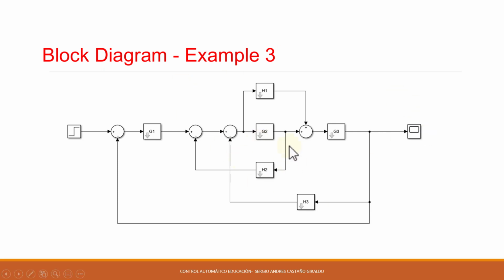So to start, let's look at where we should begin tackling this problem so we can start simplifying it. If we look at the innermost part here, where we have a branch point next to a summing point, let's remember again that this is an operation that either can't be done or is very complicated, so we should avoid it at all times. The same applies if we look at this other point here. We have a summing point next to a branch point. There's not much we can do there for now, because a sum next to a branch is something we should avoid.